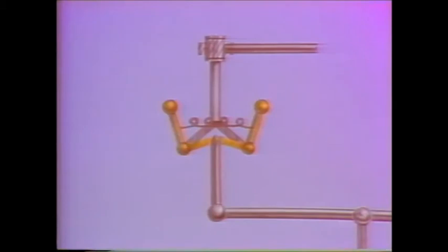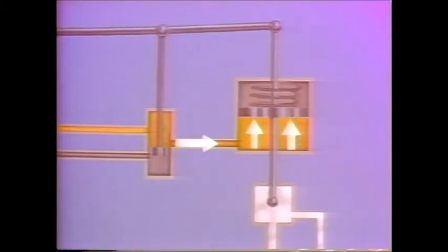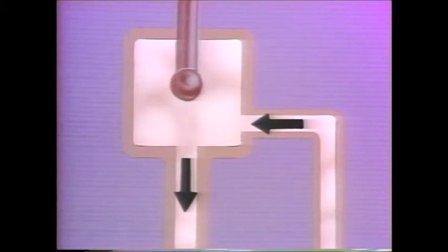If the turbine slows down, centrifugal force on the spinning governor is decreased, and the spring pulls the weights inward. This causes the bottom of the brackets to push down on the rod and the crossbeam. The combined push causes the servo valve to open, directing high-pressure oil into the hydraulic actuator. Oil pressure beneath the piston causes it to rise, and the control valve opening increases. Additional steam is now allowed to flow through the turbine, and turbine speed increases.